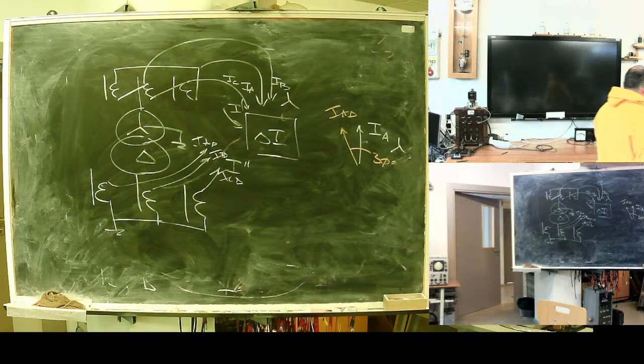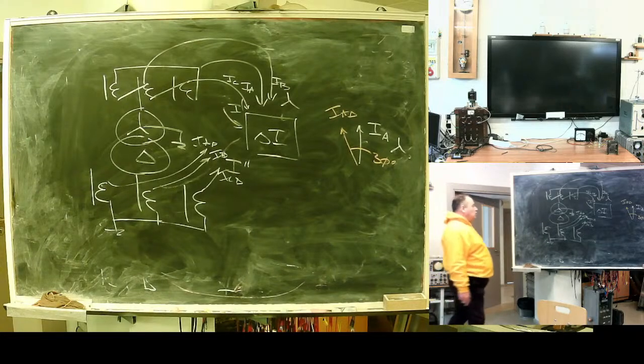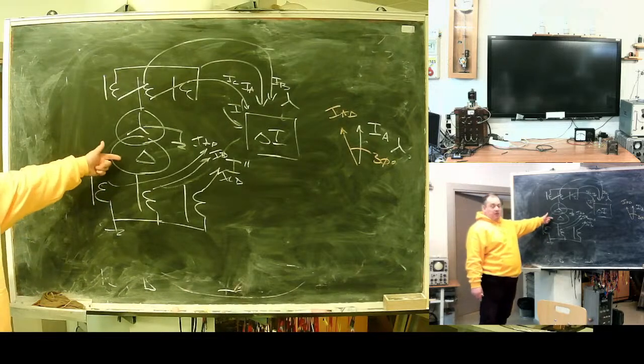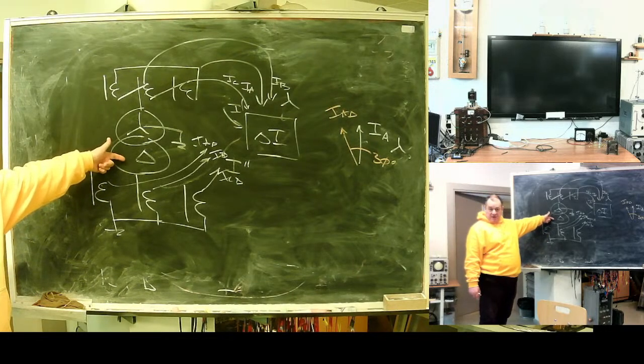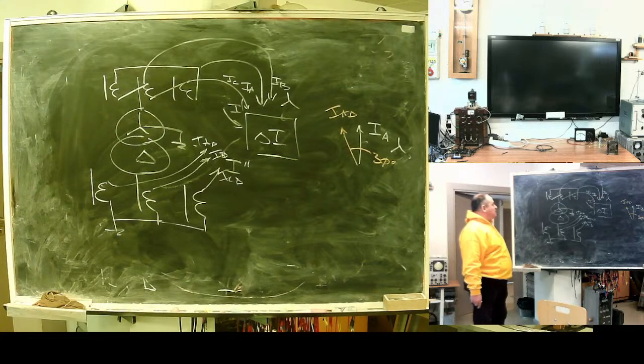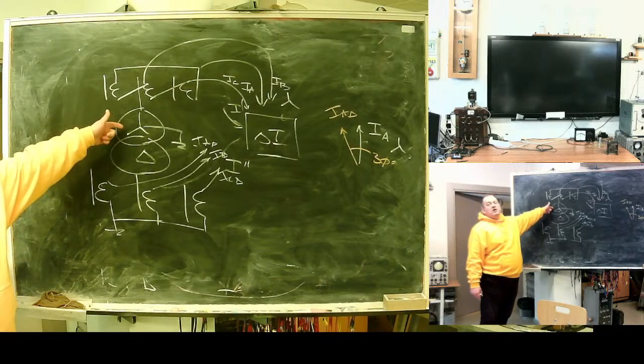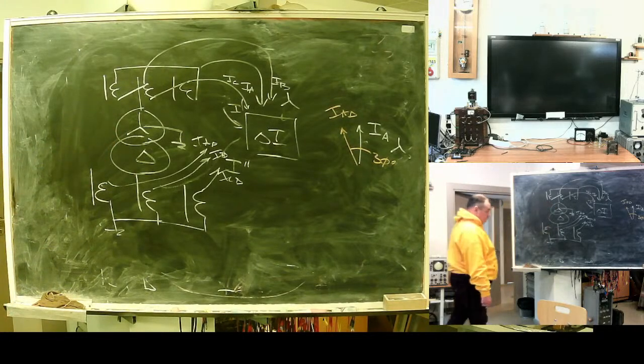It was standard for many years to use a group of interim transformers first to compensate phase shift introduced by connection scheme of the main transformer, and second to compensate transformer rate of the primary transformer.